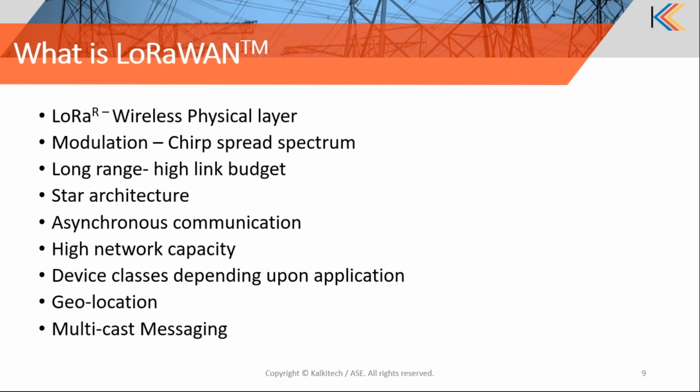So all the devices closer to the gateway will communicate faster with the gateway on high data rate, which means that other devices which are farther from the gateway will have more time to communicate. Similarly, end devices located at far points will use higher power as well and lower data rate. So with a lower data rate and higher power, it ensures that data from nodes at further points will always reach the base station.